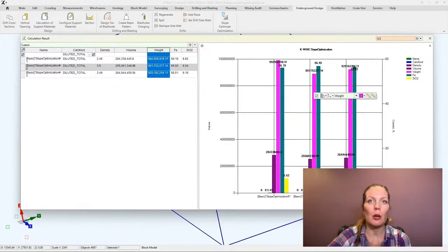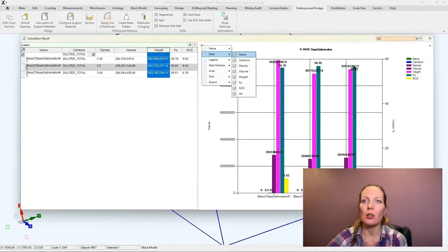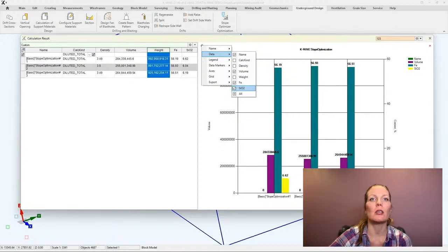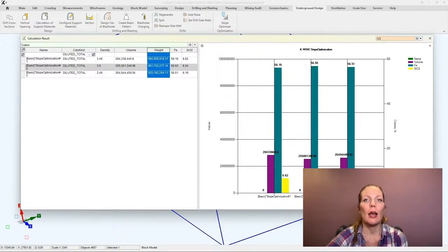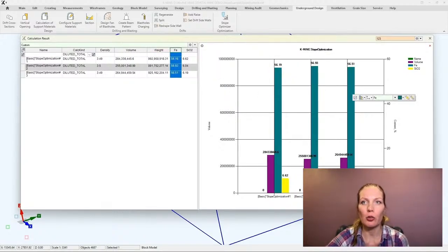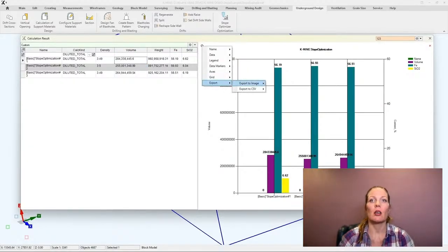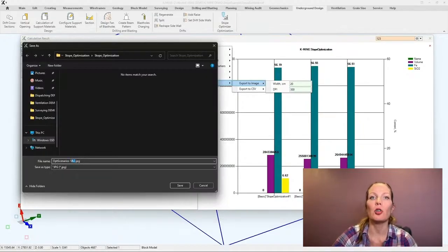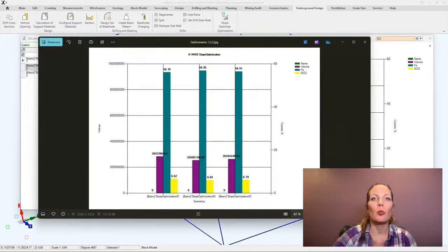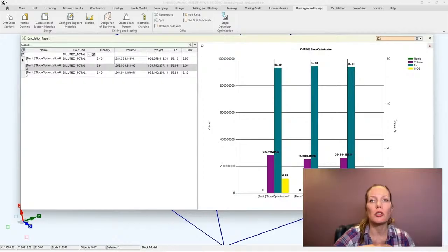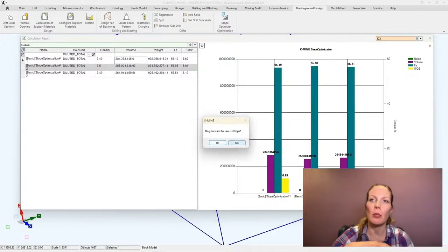Refining the stope comes next. K-Mine can adjust sidewalls, modify the stope's incidence relative to the ore body, and tighten adherence to the valuable zone. The method context matters. So for narrow gold veins, adjustments keep mining width minimal and avoid pulling barren rock. For sublevel stoping in massive bodies, refinement smooths edges and removes block model artifacts, leading to more stable drilling, blasting, and backfilling.